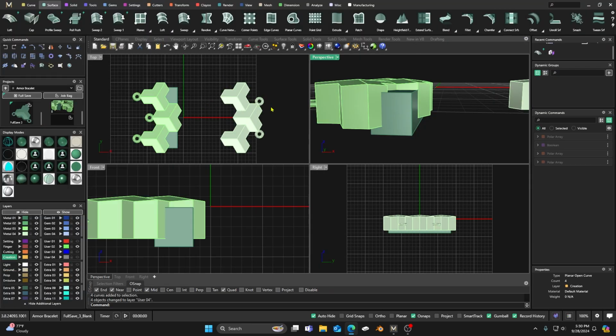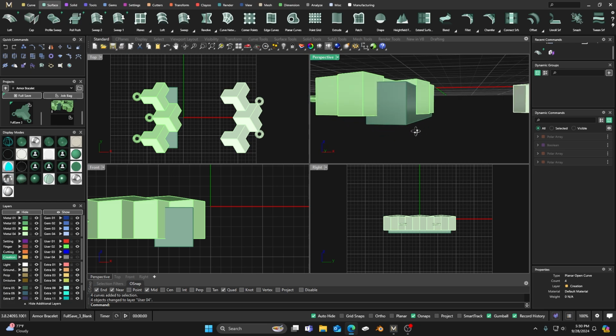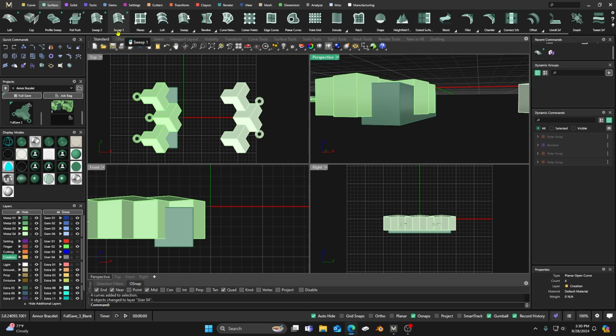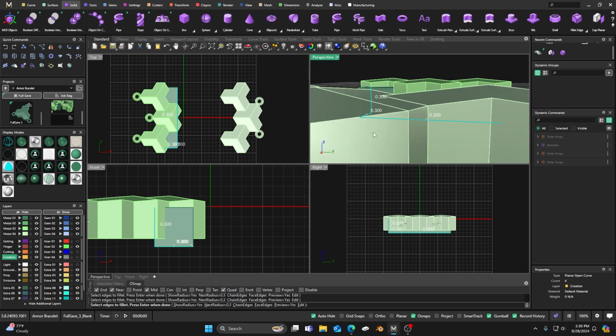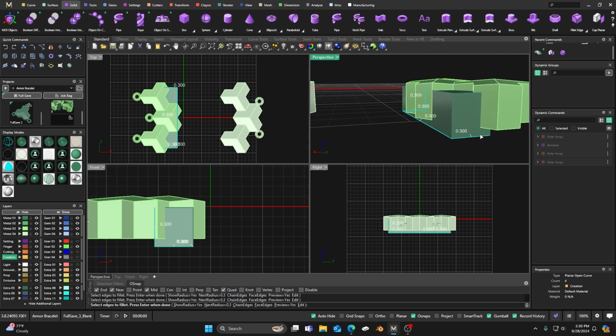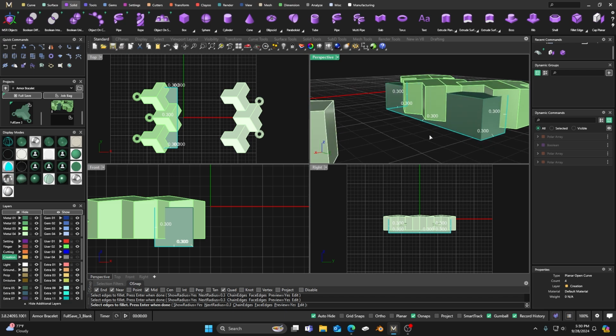But before I do that, we don't want these sharp edges down here, right? So we're going to see if we can work on that here. We'll go to fillet edge. We'll select this edge, and this edge, and we'll swing around to our other side here and select this one and this one. And we'll just right click, and I got preview on, yes, and I set it at a 0.03, and I'll just accept that.